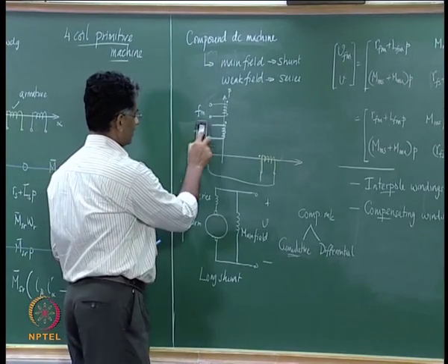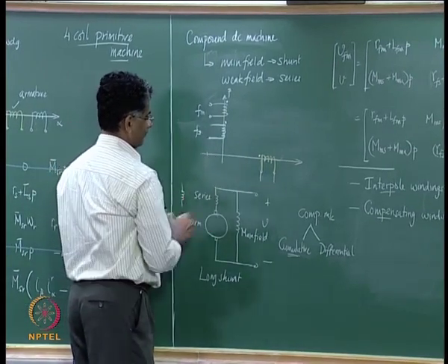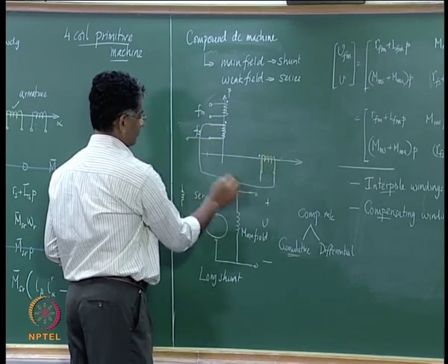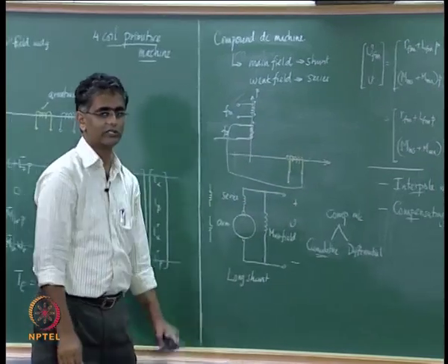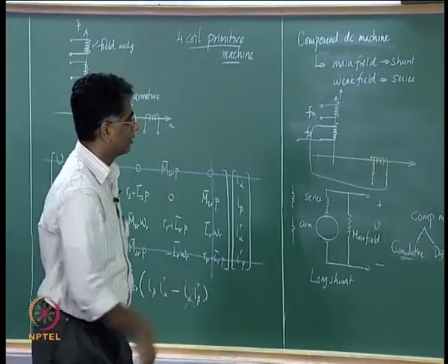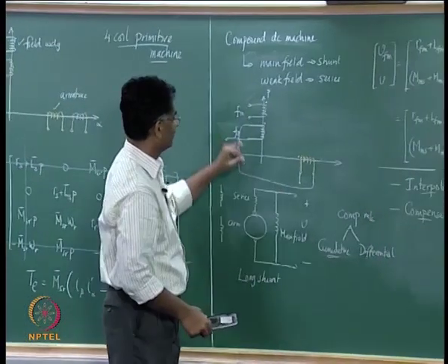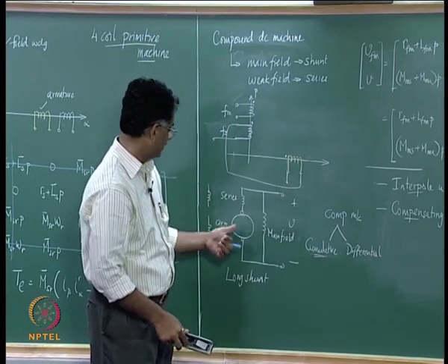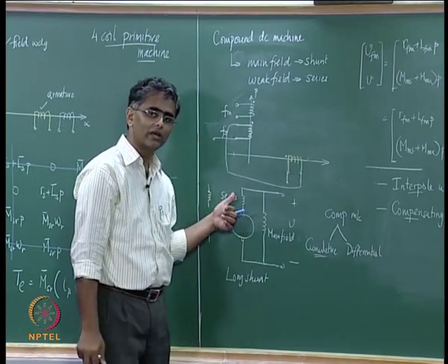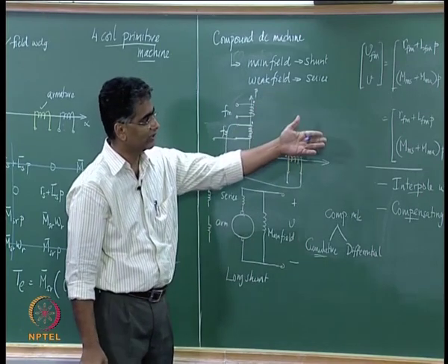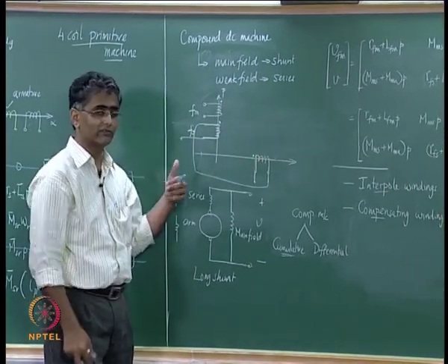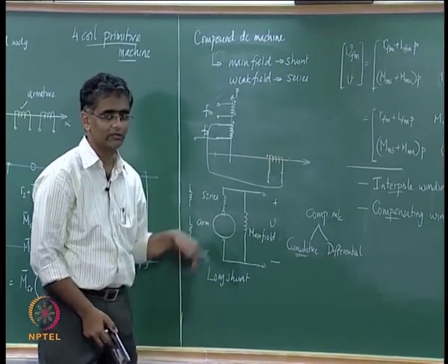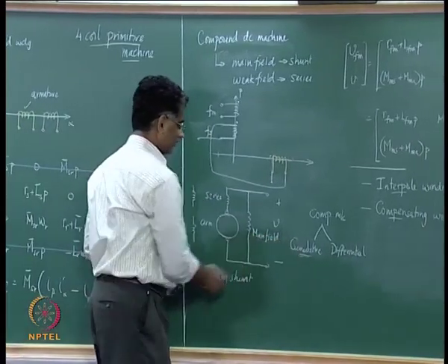What we had implicitly done was connected this way. So, the armature voltage was applied between these two terminals. So, accordingly we have written it. If it was the other way around, then you would have had a situation where IA is equal to minus of IFS. Then with that, if we derive the expressions, you would get the equation for the differential compounded case. We had instead said IA is equal to IS, and therefore you have the case of the other variety.